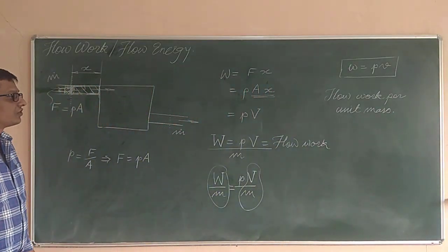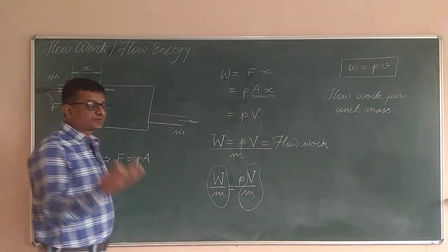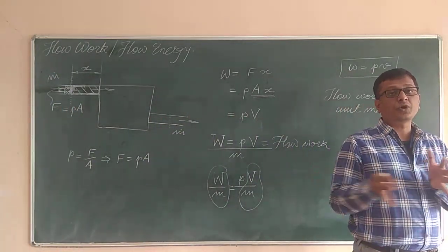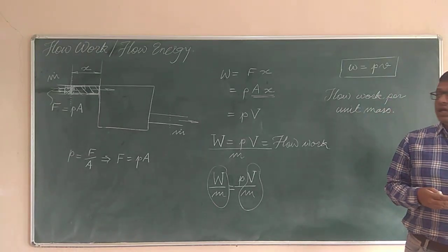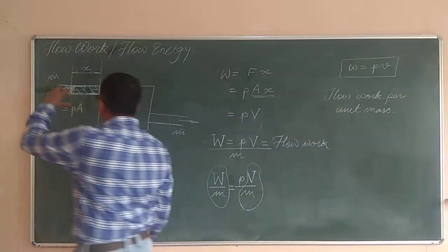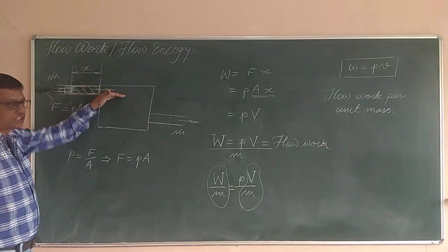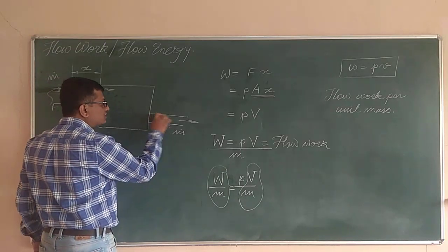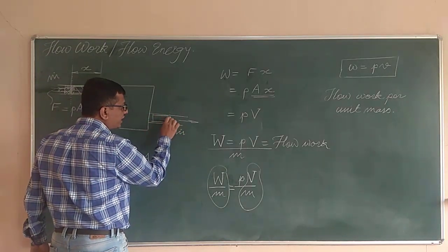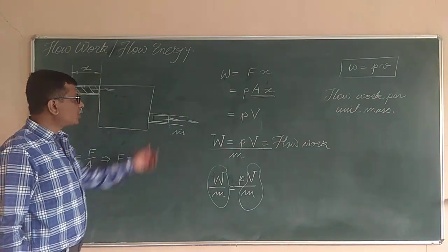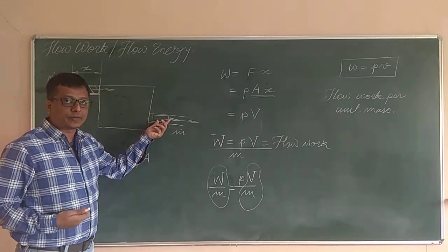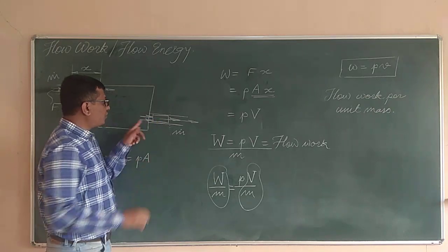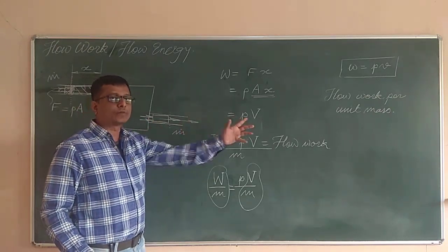We also say it as the flow energy, or the transport energy, since this is the energy related to the transportation of the fluid from one place to another. By the way, this flow work is present in the fluid which is flowing into the system. At the same time, the flow work is present over here also, since this fluid element is also flowing ahead and going out of the system, and it is not happening automatically. There has to be some force acting on this fluid element, and that force will push it ahead and kick it out of the system.